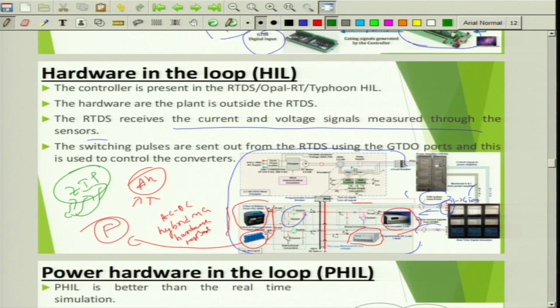And then let's say this DC microgrid is operated in an isolated fashion. They are not connected to any external system. They are independent on themselves. That's what microgrid means. Microgrid means they have their own energy source, their own load, their own storage component. They can independently sustain even if they are not connected to the infinite grid. So if they are operating in an isolated fashion, what happens?